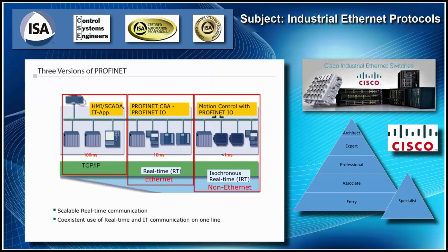The 3 protocol levels defined for PROFINET include PROFINET TCP/IP. PROFINET TCP/IP is used for non-deterministic functions such as parameterization, video and audio transmissions, and data transfer to higher-level IT systems. PROFINET RT. The TCP/IP layers are bypassed in order to give deterministic performance for automation applications in the 1 to 10 millisecond range. This ability represents a software-based solution suitable for typical input-output applications, including motion control and high-performance